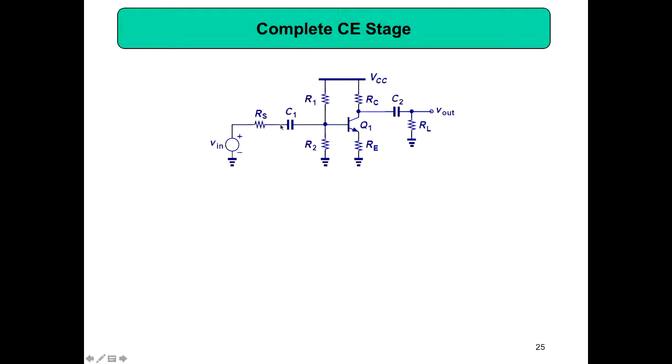So this capacitor is called a coupling capacitor, and this is to isolate your DC voltage from the signal you connect. We will study about this capacitor in the coming slides. So this is called a coupling capacitor. Again, you have got a coupling capacitor at the output.